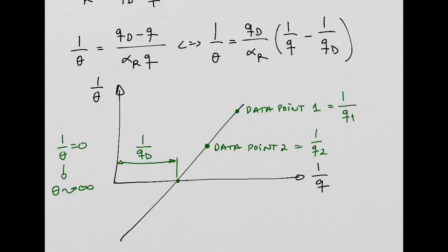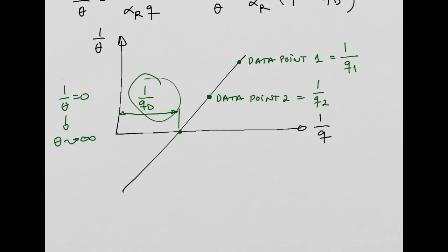And then, once you draw that line, you find the intersection of that line with the horizontal axis. And then you get, immediately from the wind tunnel, your divergent dynamic pressure. And of course, your divergent speed. Only from 2 measurements in the wind tunnel. That's what this equation is telling us. And that's why I'm doing this. So I showed you how you can get analytically the divergence velocity, and I'm showing you now how you can, in the wind tunnel, get your divergent velocity as well.